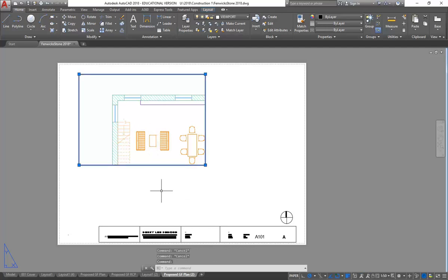How do you go into model space if you've got a viewport on a page like this? So, how do you go into model space? If we want to do things in this viewport, we've got to go to model space. Yep, there's three ways. That's good if you remember any of those. Yeah, so the one down the bottom, that's good. The paper button, that makes the viewport active. In other words, we're in model space, and you can see down here now it says model. If I click where it says model, it goes back to paper, of course, telling us that we're in paper space or working on the sheet. So that works using the button at the bottom.